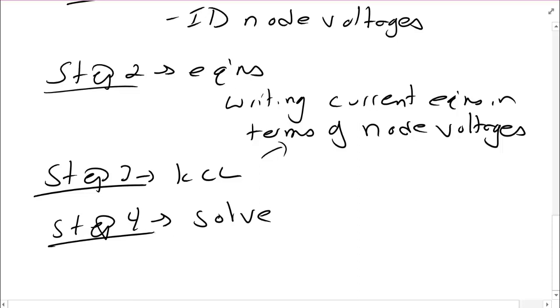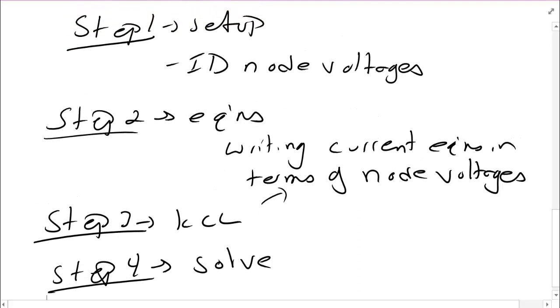What's very important in this course is that no matter what we do, we'll always have n equations and n unknowns. Those unknowns are going to be the unknown nodal voltages. Those equations are going to come from KCL. The equations are also always going to be linear equations, which means we can always solve them. As you progress through circuits, you might learn about elements that are nonlinear. Nonlinear elements unfortunately can't be solved in a nice way. However, the very large majority of circuit elements that most people encounter are going to have linear properties. So as long as you remember our 4 steps, you can solve most of the equations in this course.